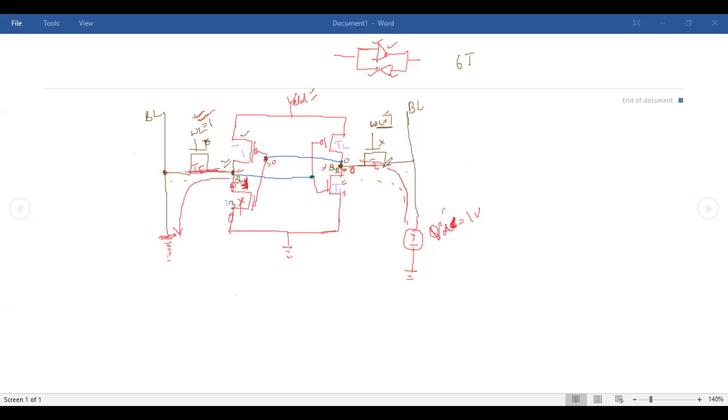So this tries to charge this bit from this side because this is short. Now this QB will be charged to 1 only in case this transistor gets turned off. When your Q equals 1 gets discharged from here, when it reaches the value VDD by 2, below VDD by 2 to be precise, this transistor gets turned off. When this transistor gets turned off, this potential easily gets written to QB equals 1.